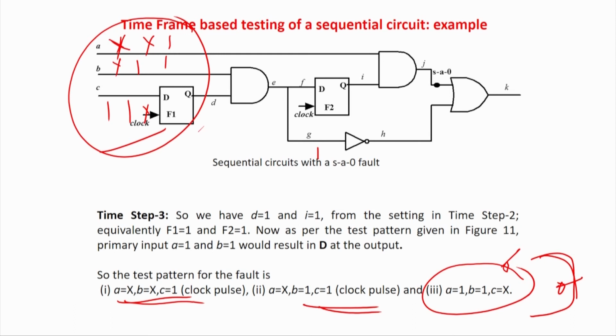So you have to appreciate the fact that if there are 10,000 flip flops in the dependency list, or the depth is 10,000, then the ATPG will also have a 10,000 step ATPG in the worst case. So test pattern generation will be very, very complicated. But once I have done that ATPG, it has told me that these 3 patterns are required. Now I have to apply them. So I am applying first this, second this, and this, and your job is tested.